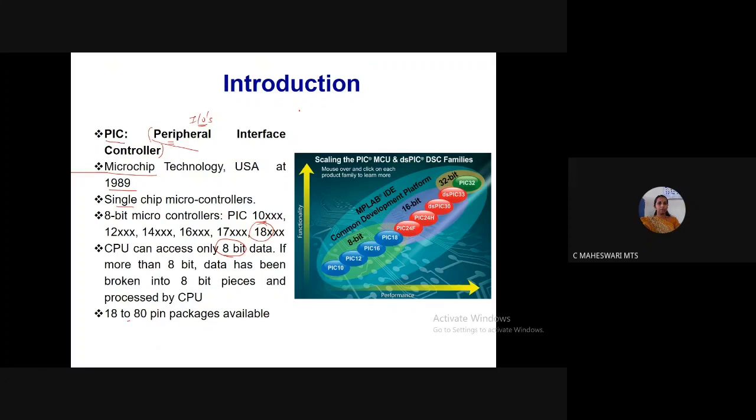Here it's not like the 8051 microcontroller, which has a 40 pin IC and a fixed number of IO ports. Within the same PIC18 microcontroller family, we have so many variants: some microcontrollers have 4 IO ports, some under the series have 5 IO ports, some have 3 IO ports.